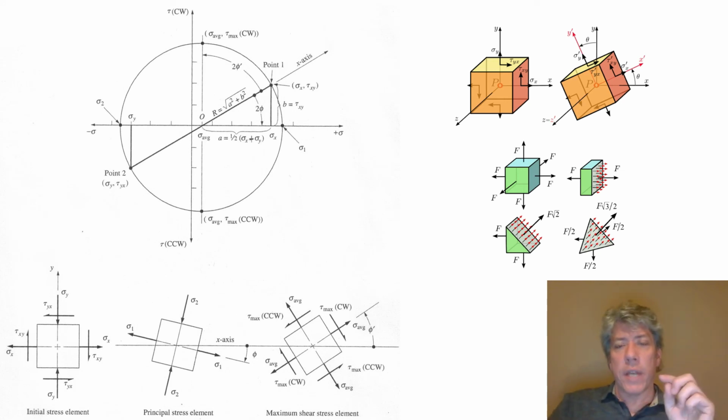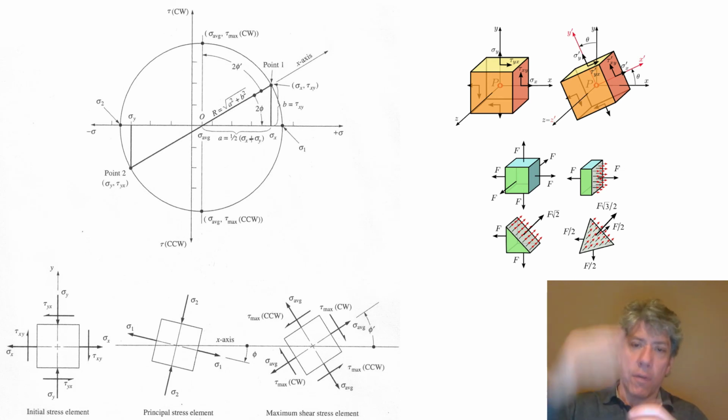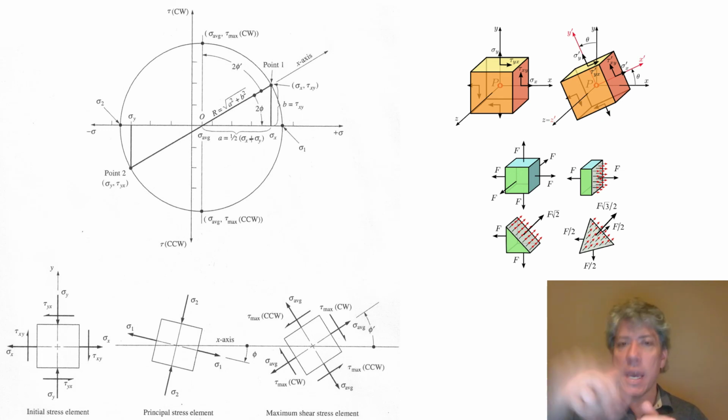The reason for that is you're probably pulling apart either steel or aluminum dog bones, both of which are typically ductile materials, unless of course they've been heat treated and quenched and so forth. But in that case they would be brittle and they would just break horizontally. But most of the time we give you guys ductile materials to pull apart, and so you see necking down, and you see a failure plane that is not just straight through the dog bone, normal to the axis of the dog bone. Rather, what you see is an angled plane.